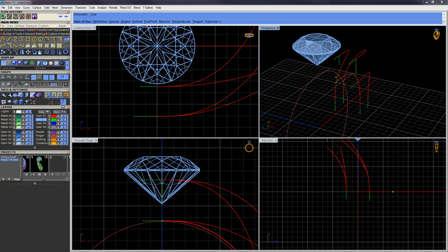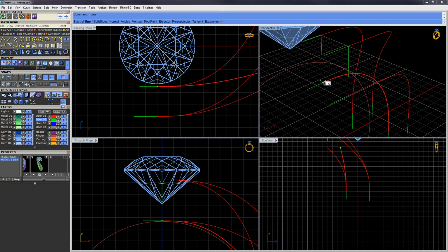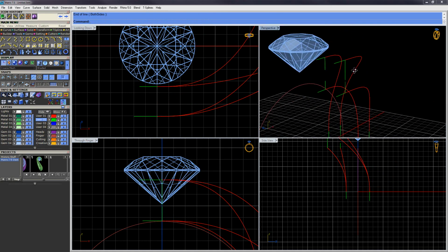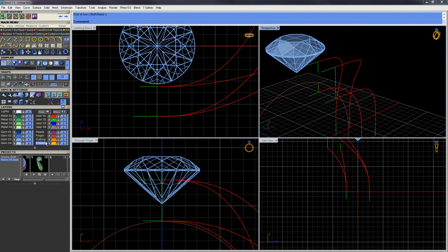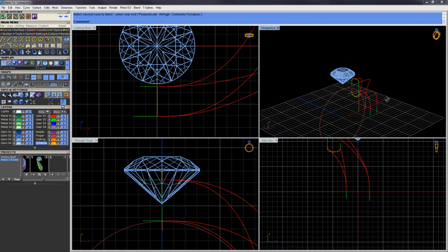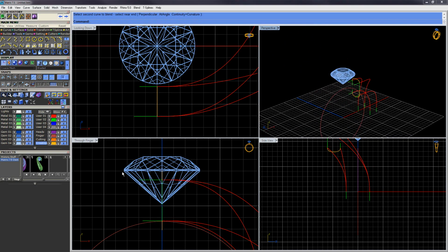And again, these are simply for creating a small profile using blend. And again, if I use this technique, everything that I adjust, once we show you how to adjust this, everything blends together. So let's make our creation layer there, and let's do a blend curves again from here to here, and then we'll do another blend curve from here to here. Right. At this point we have the basis for pretty much everything that we need to finish the ring.